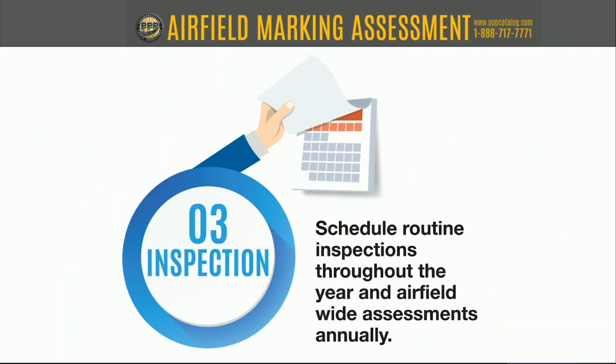Yeah, that's great advice for dealing with those situations. And yeah, I'm familiar with that particular situation, and you're right. In this case, I think it had to do with the deviation. You put a retroreflectometer on it and it passed, but then it still didn't look right. And that's where we talk a lot about this inspection needing to make sure that you incorporate the three methods. Incorporate the visual with all of these.